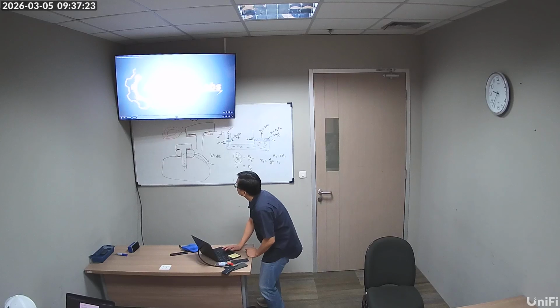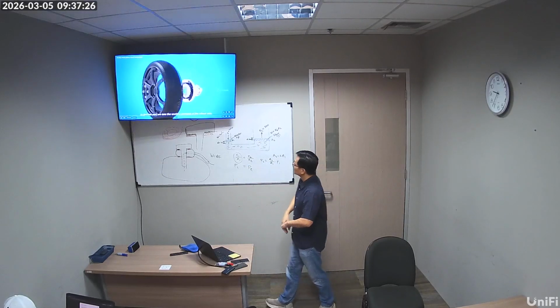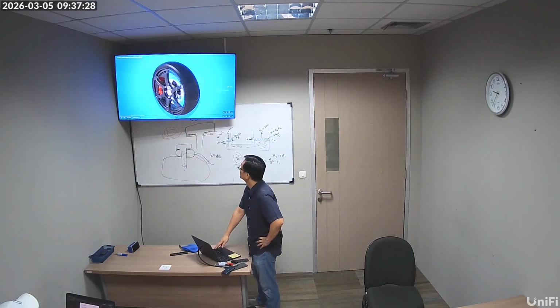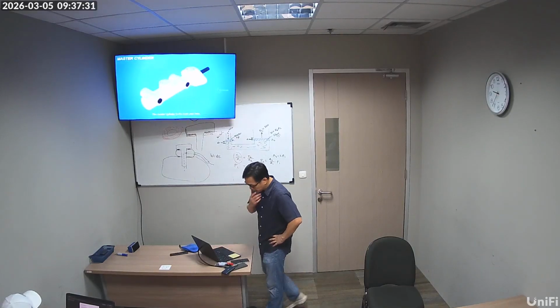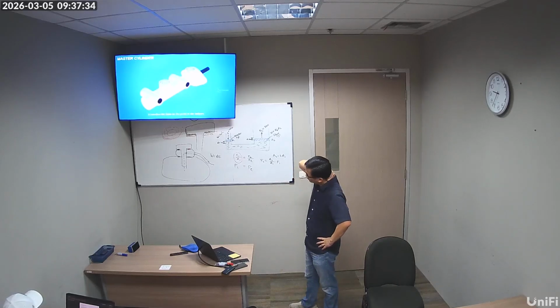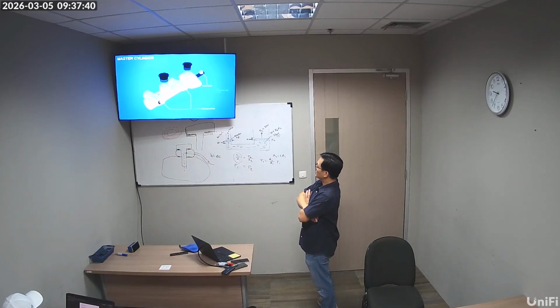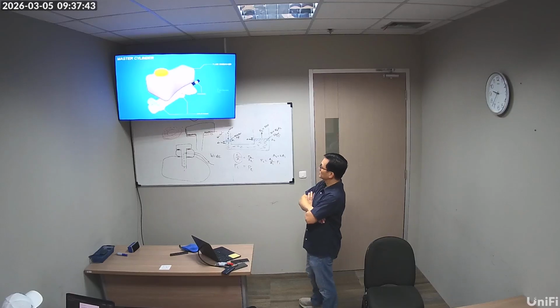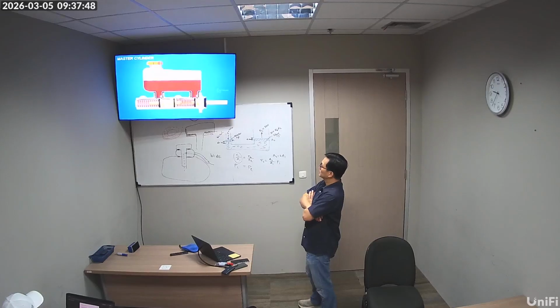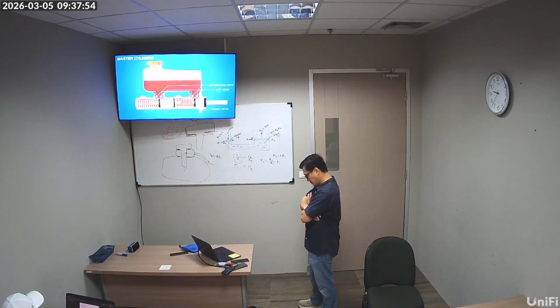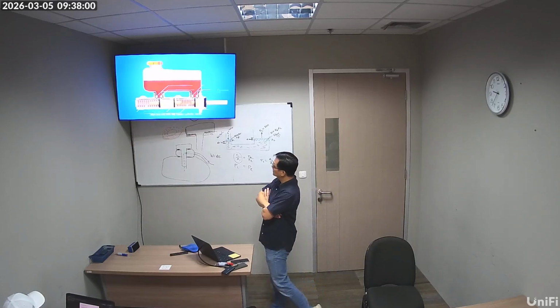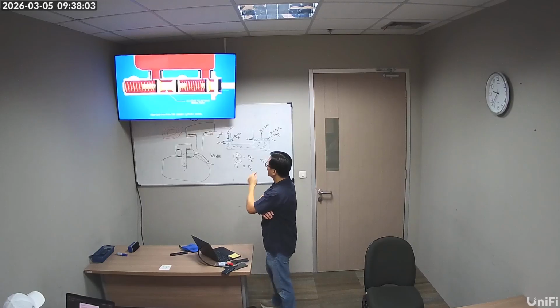How the brake system works. In the last part, we saw the working principle of the wheel side. The master cylinder is the main part here. It transfers the force on the pedal to the calipers. There is a push rod, outlet port, and a fluid reservoir tank. Let's see what's inside the master cylinder. There are inlet ports for the fluid to reach the cylinder, compensating ports, primary piston, secondary piston, retaining springs, and piston seals.